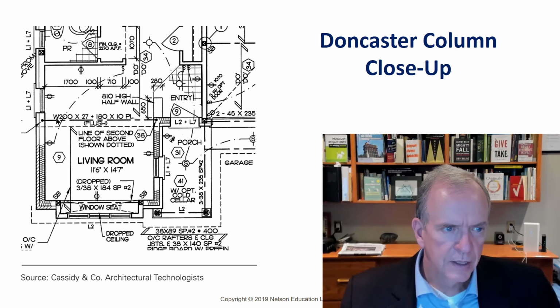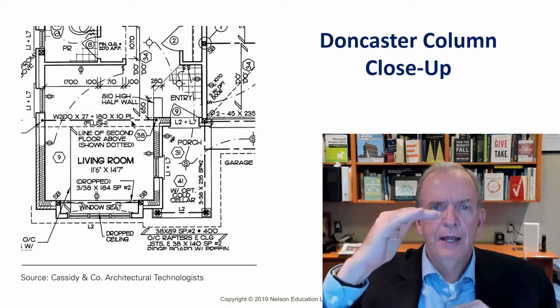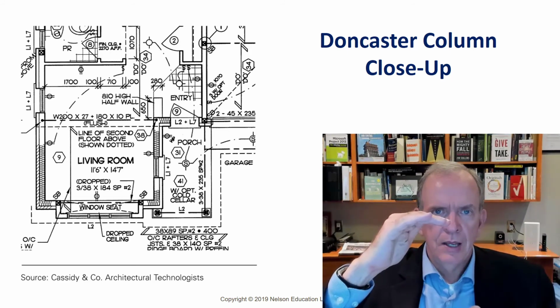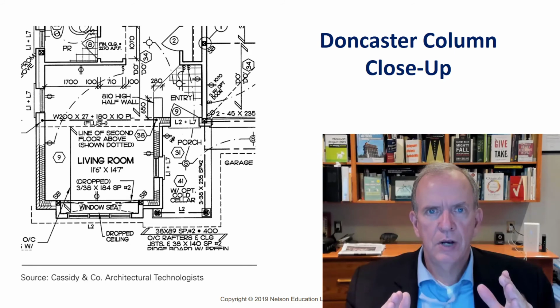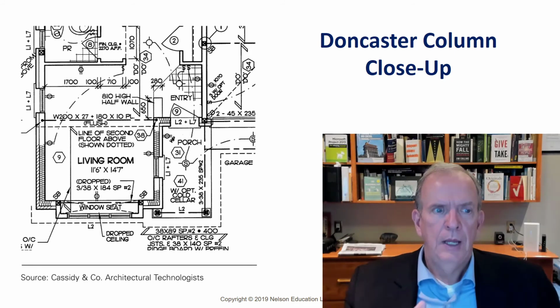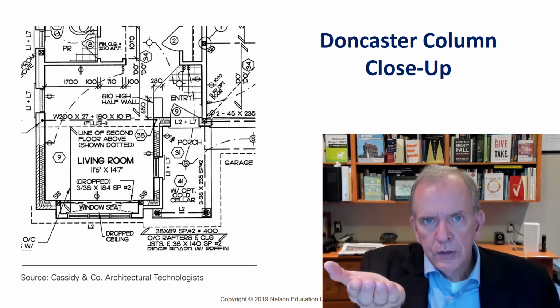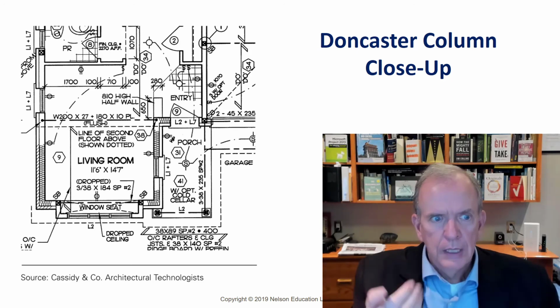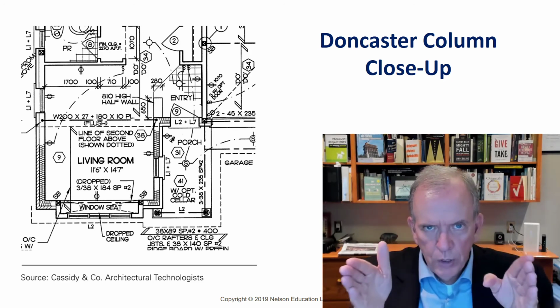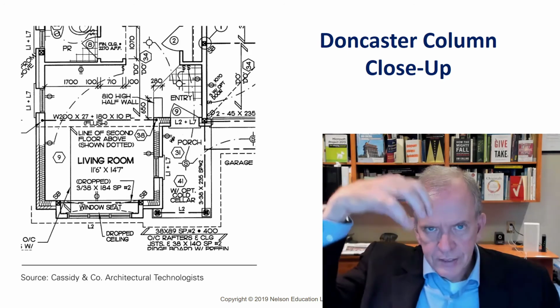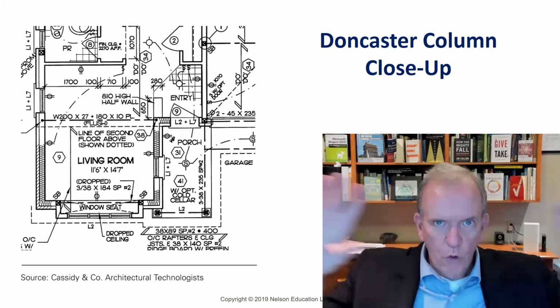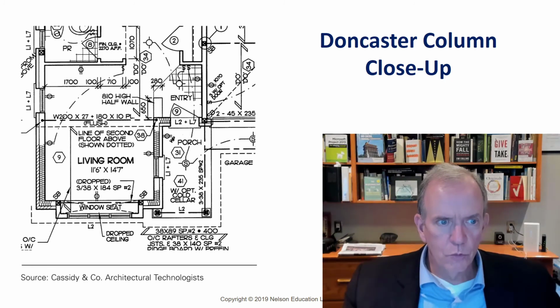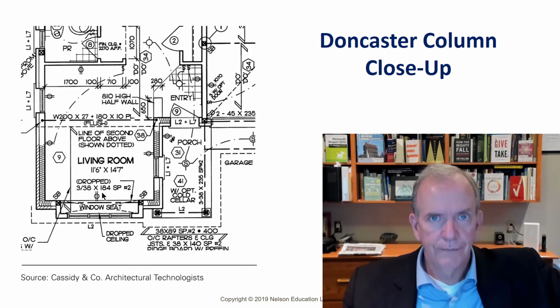It's supporting this W200 by 27 by 180 by 10 PL. So it's a wide flange I-beam that's 200 millimeters high. It weighs 27 kilograms per meter. It has a steel plate welded underneath it to the bottom that's 10 millimeters thick by 280 millimeters wide. And that steel plate is going to carry the brick over the second floor. But in the room, there's going to be nothing. You won't know it's even there. It's going to be just a smooth ceiling.